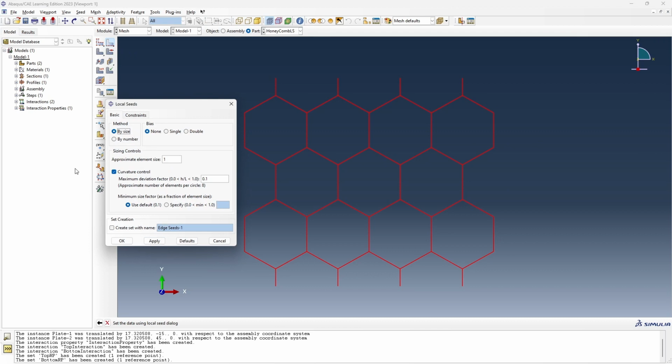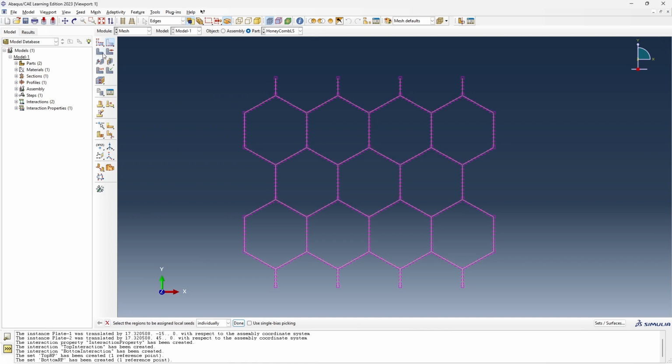Remember, in Abaqus student version, you have a mesh limit of 1000 nodes. So just keep that in mind when you're meshing. So press apply, click OK. Now press mesh part, click yes. And as you can see in the window here, it shows 500 elements have been generated, which is well below 1,000, so it'll be fine for now.